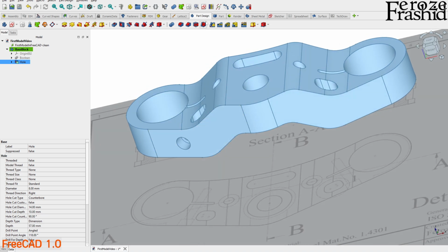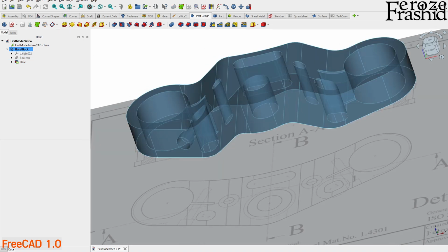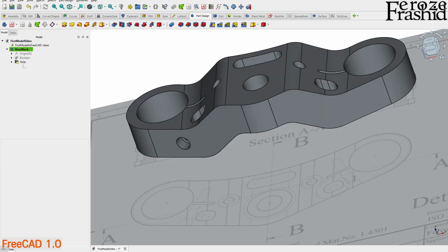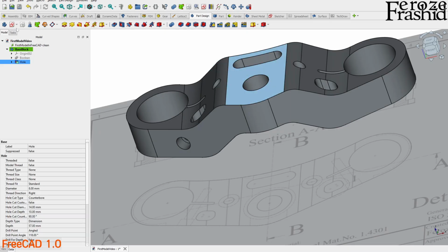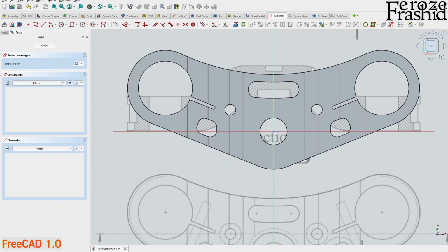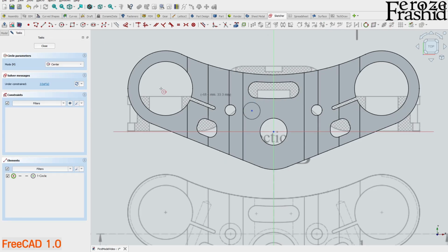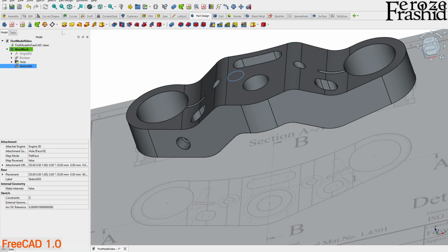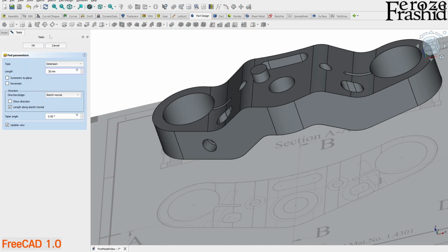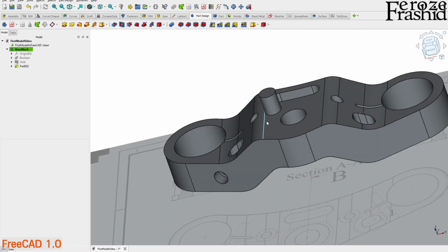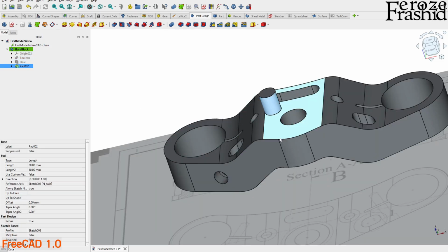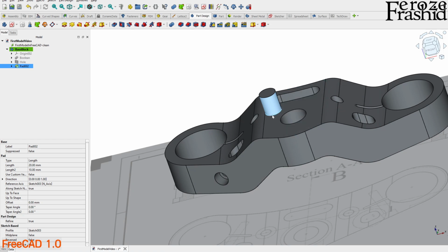And that's the beauty of Part Design. If you are working within the same body, anything that you work on is built upon the previous feature. So if you added something up here, for example, you select this sketch, draw another sketch on here, for example for a circular tower, and then extrude that for 20 millimeters. By default, because it's within the same body, it is added to the previous one because it was an additive feature. If you made a hole instead, it would cut through.